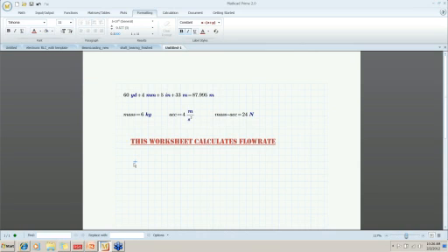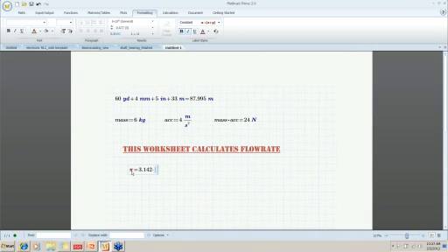So if I type in pi equals, and I'll zoom in a little bit, you'll see pi is by default this maroon dark red color, because that's a built-in constant in Mathcad. That's one built-in constant of several. So this is where you can apply what we call label styles.